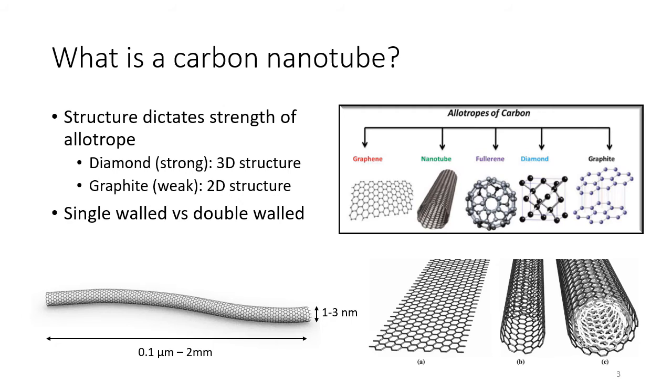Diamond, graphite, and carbon nanotubes are all allotropes of carbon. Carbon-carbon bonding is incredibly strong, and the 3D structure of diamond takes advantage of this to provide hardness and strength in all directions. Graphite forms in individual planes, a 2D structure, and as a result it is incredibly weak in shear and does not take full advantage of the high carbon-carbon bond strength. CNTs take advantage of the strong carbon-carbon bond in a high aspect ratio 3D structure that is extremely strong, stronger even than diamond.